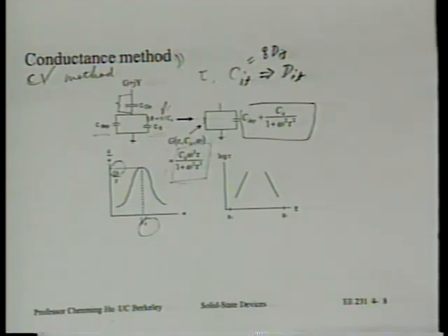And although it's a very important problem, because we are looking at dramatically different new ways of making the gate dielectric, perhaps using nitride, perhaps using other high-K dielectrics, you find that we're at the same time somewhat behind in our ability to characterize the interface. So that's an interesting area for research.